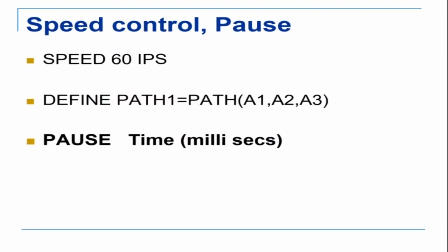The other commands that are there are speed IPS. IPS means inches per second. This is the end effector speed. It can also be meters per second, so MPS is meters per second. Yeah, this is also available.